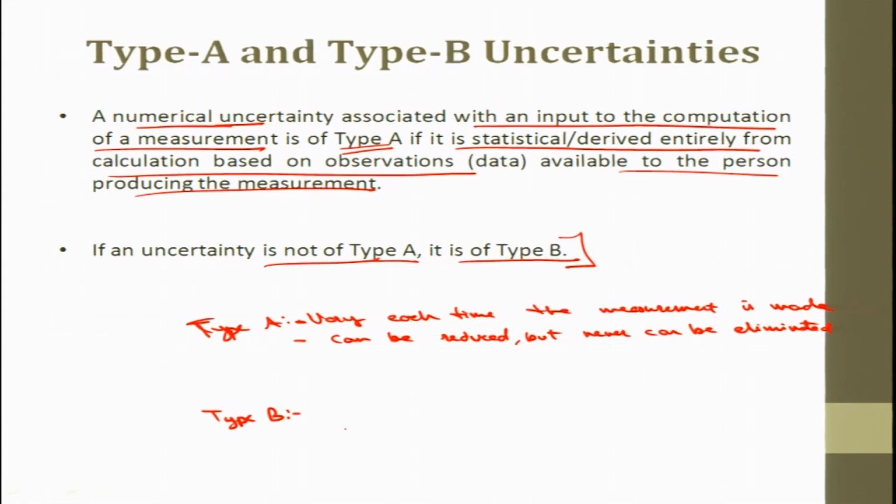A better calibration can quantify type A uncertainty, and calibration can reduce the level of type B uncertainty as well, but there will always be a small amount of uncertainty that would be left in the instruments. So type B uncertainties are mostly systematic, if not always. A few examples here can be like thermal stability.